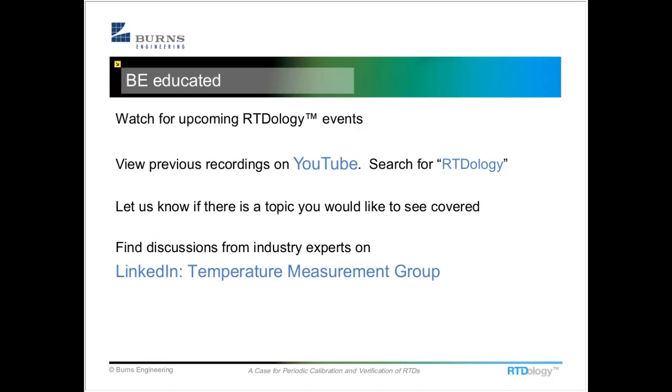The coil style elements, and that was an example of the one that we looked at earlier with the insulation resistance check, those coils can only be supported a certain amount, and if you try to support them any more, they tend to induce a lot of strain, and then your resistance number is going to be very erratic and not repeatable.